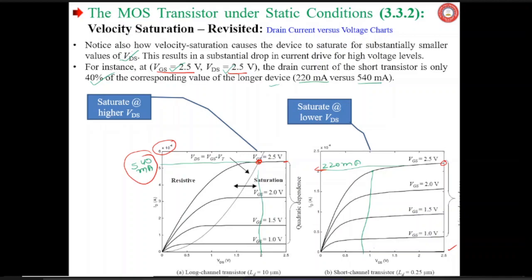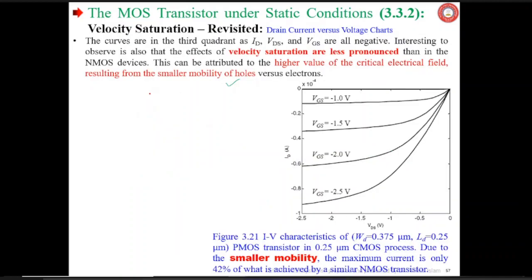After drawing the structure, if you apply voltage at the gate, how is the voltage affecting the channel region? In NMOSFET, the channel is formed with electrons. Inversion layer is of electrons, whereas in PMOSFET it is with holes. That we discussed or not? Yes, sir. We discussed. Okay.